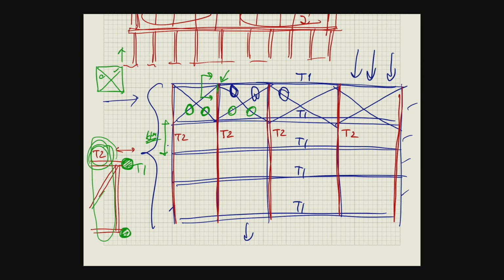Okay, so what I'm trying to say is that only one out of 2 is going to carry the load. Then when you design, in your design, you have to design such that only one can contribute the stiffness to meet the requirement. You don't take 2 and just give them the equal amount, because the one under compression is not going to work, and then you'll be in trouble.